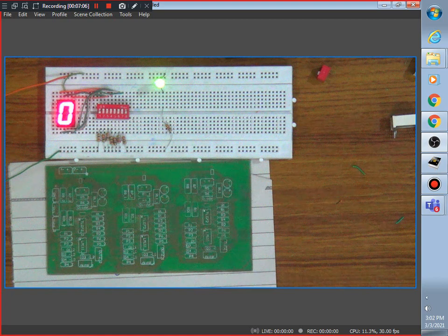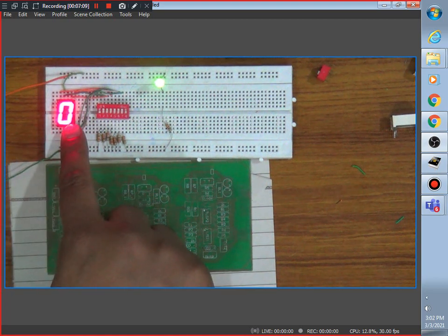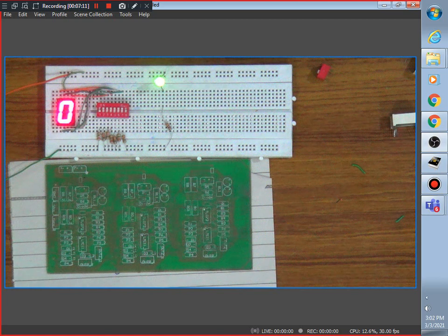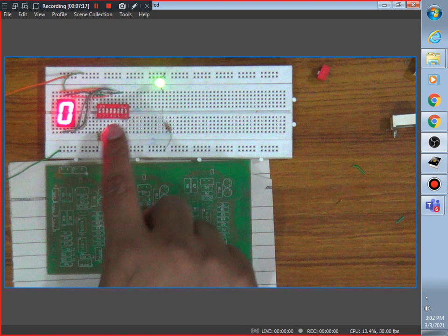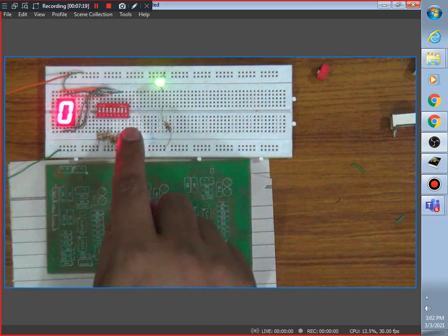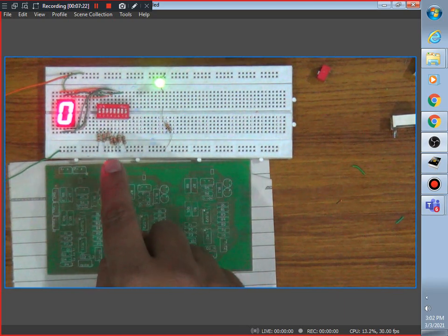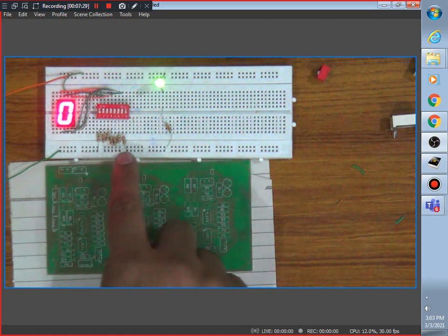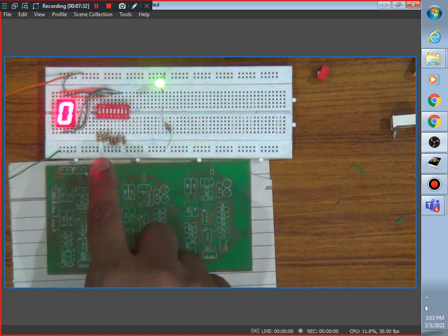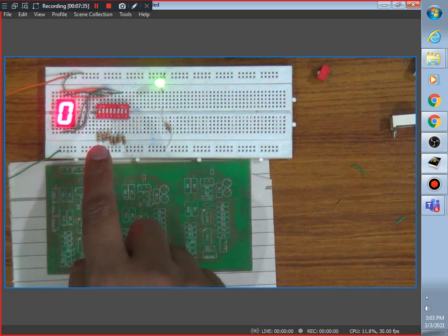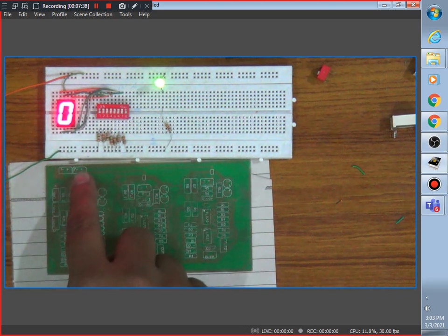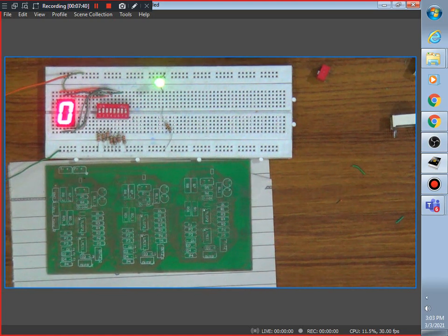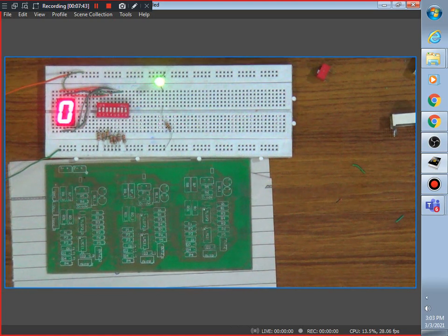So the 7 segment of this size, which is in front of here, is going to have a footprint. Now, the footprint of this dip switch, this is a dip switch. Why? Because I told you previously, a DIP means dual inline package and the spacing between the pins is 2.54 mm. So this is a dip switch over there. Plus these resistances, these are axial resistances over here, because they have just 2 ends. You can just put one end in one hole and the other end in the other hole. So you need footprints for all these 3 components.